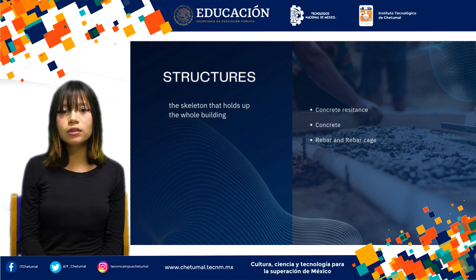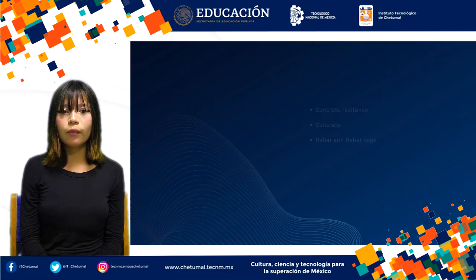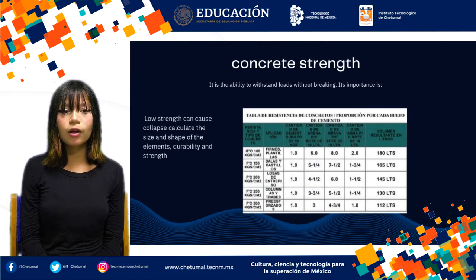This is one of the most delicate processes as it defines the depth and type of foundation that will support the entire structure. Types of excavations. Excavations vary depending on the type of foundation being built. They can be shallow for small houses or deep for larger structures or difficult terrains. Use of machinery. Most excavations are done with backhoes, although in smaller plots or hard to access areas, manual excavations may be necessary.